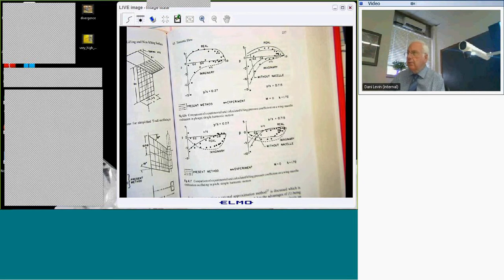The Europeans seem to like to do this more than the U.S. people. Typically in the U.S., there are a lot of aeroelastic models. They're flutter models, or gust models, right? These are major responsive systems. The Europeans seem to be more prone to oscillating the model in some prescribed motion, measuring the aerodynamic forces, comparing it to the theory, correcting the theory based on the difference between the experiment and theory. They'll fudge a coefficient here or there, and then they'll do a flutter calculation. And they think that's a better way to go. And so when people get together from the two communities, they have a debate about which approach is better.